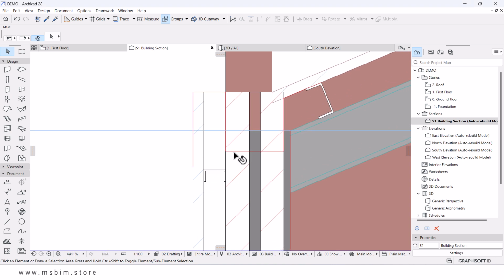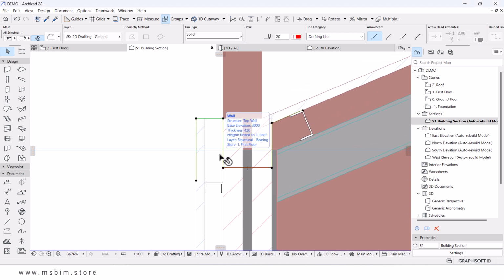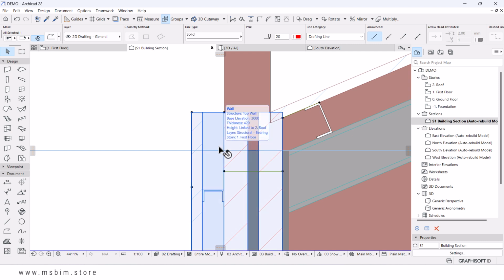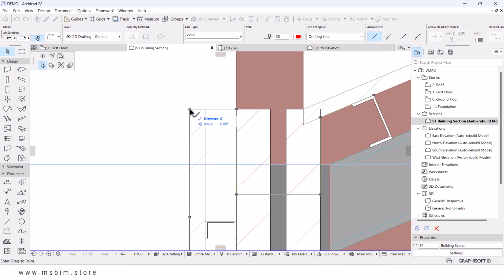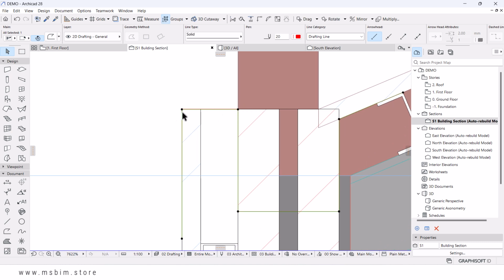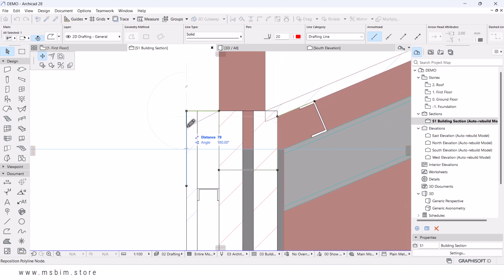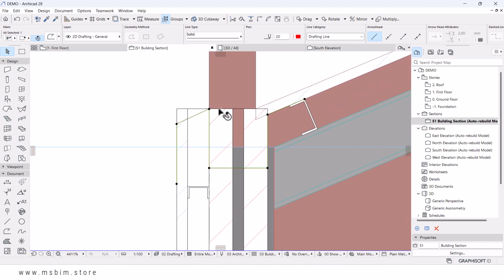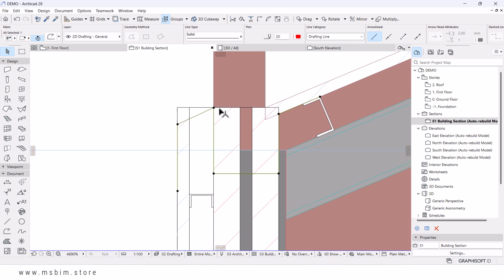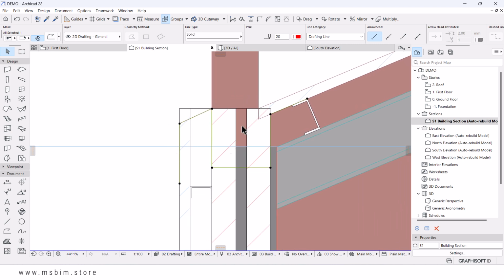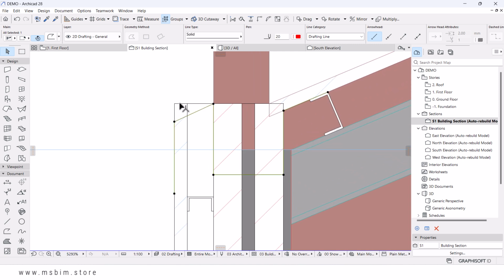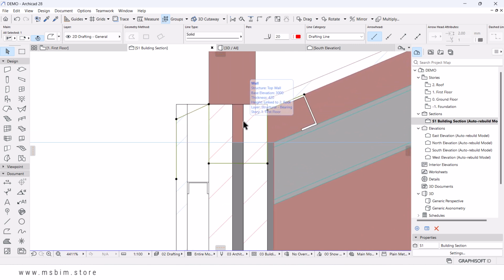All right, so we can customize or tweak a little bit the profile of our gutter, but for the sake of this, I might have to just angle it a bit, because for purpose of rain, you don't want to have a flat surface like that. I want to promote this by angling my gutter at the edge like that, so that I allow for the flow of water not to be held on top of the gutter like that. I hope you understand what I'm trying to say.